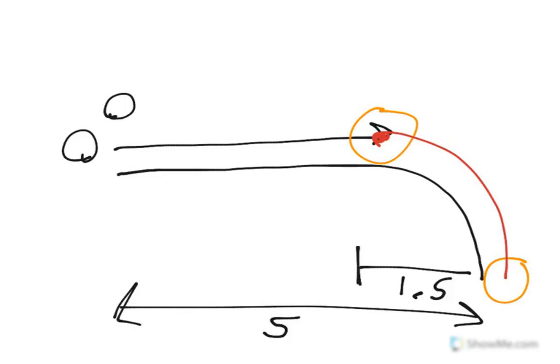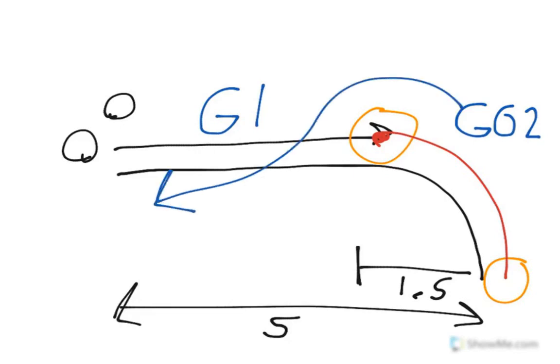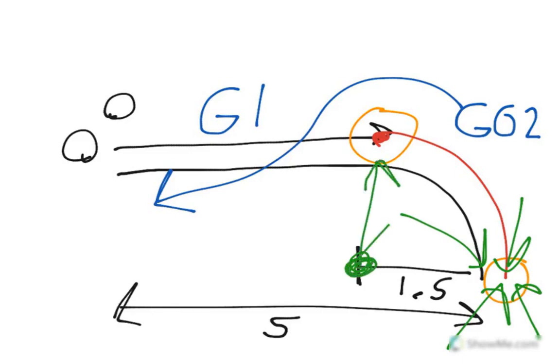So just to write down a few notes for the code we're going to be using. This first portion is going to be a G1. This next portion here is going to be a G02 as we move around counterclockwise. But when we use this code here, we need two things to actually input. We need to input the final location that we're going to arrive at, which is here. And then we also need to know the distance from the center point of our arc, from here to here.